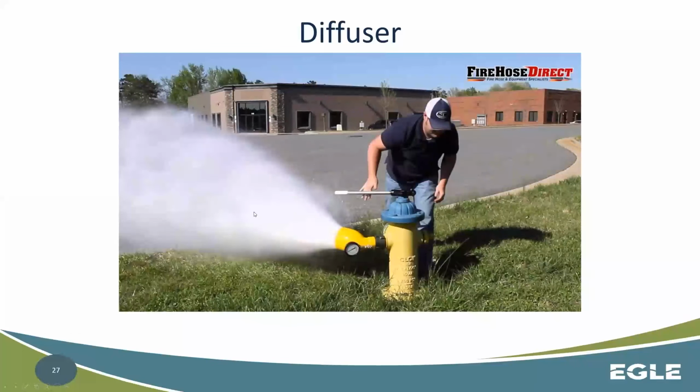These diffusers help do two things. They help diffuse the water, but then also dissipate the energy that's coming off. So you can still flow these at quite high volume rates. You can actually sometimes get a gauge on here that's calibrated that will tell you flow. And if it doesn't tell you flow, it can tell you pressure. So if you have another static pressure gauge upstream or downstream or both, you can look at the pressure drop in relationship to the pressure that's coming out of this, and you can do some calculations to figure out flow pretty easily. But this helps so that you're not eroding ground, you're not tearing up curb back. You can blow it out this way without literally tearing up all the infrastructure that's around it.